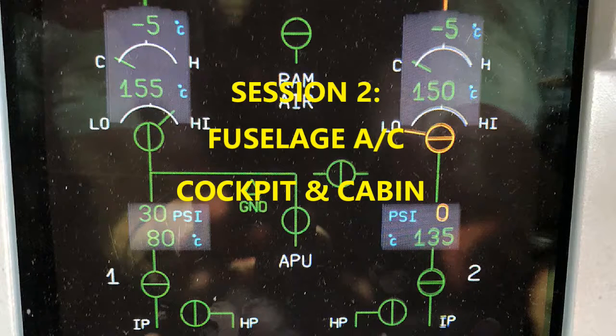And you have pressure sensors, because everything I mentioned up to this point was about temperature. Those were temperature sensors for temperature control input. Now there are pressure sensors, but they're pack inlet pressure sensors. The pack inlet pressure sensor senses the pressure of the bleed air that enters the air conditioning packs. It sends a signal to the pack controllers, which affects the flow control valves. They're installed upstream of the flow control valves.